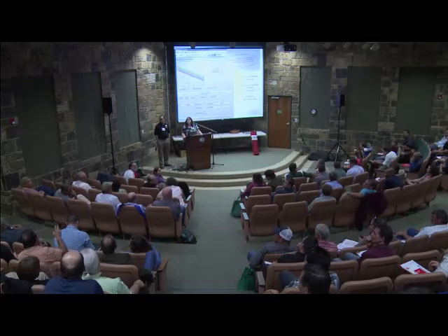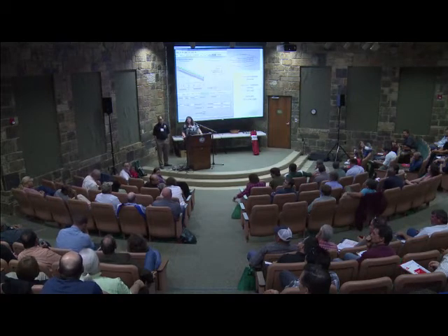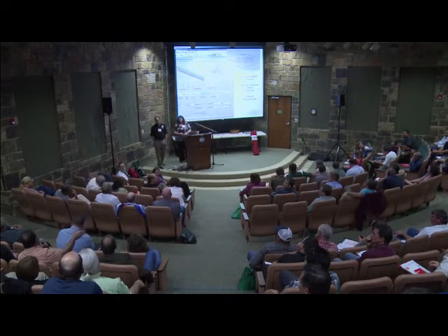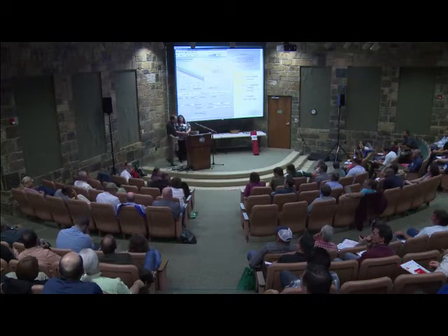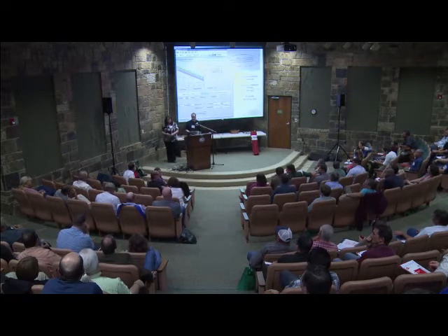The 9% slope you mentioned earlier, is that the steepest slope you get, or the average slope? On the EPA construction general permit that we worked off of as part of the stakeholder group, the original version of this for several cities across the U.S. used the 9% as their criteria, so that's what we went with.